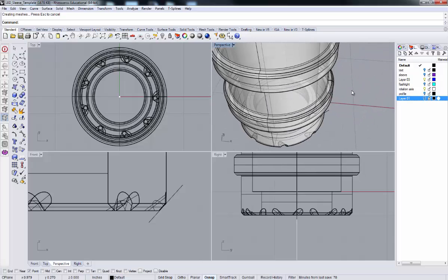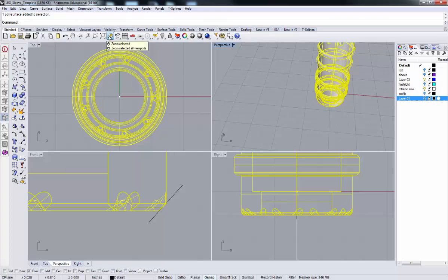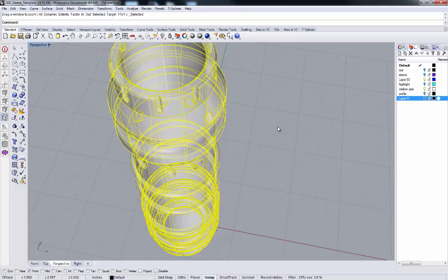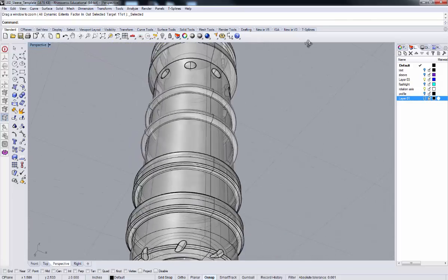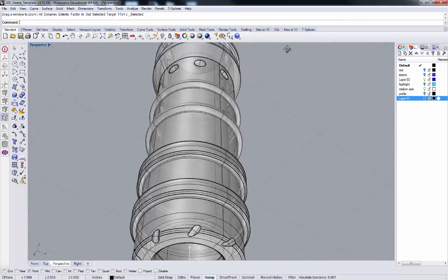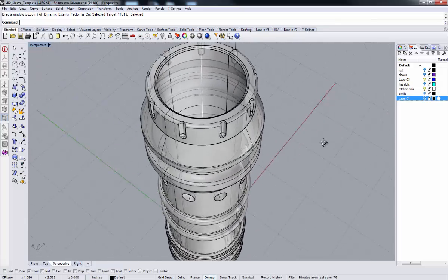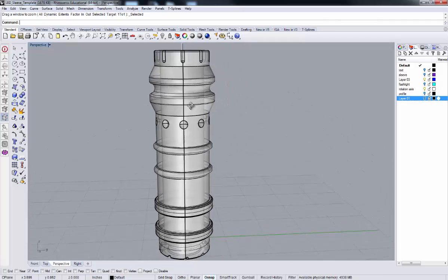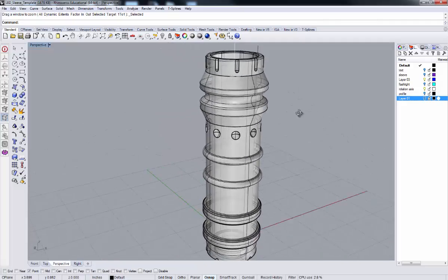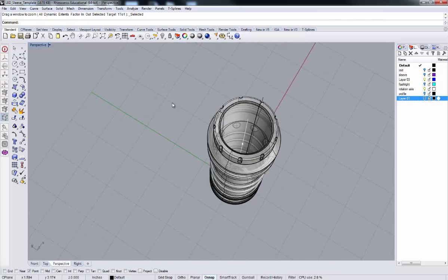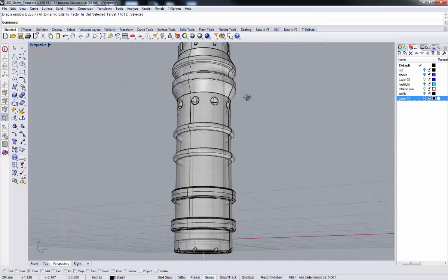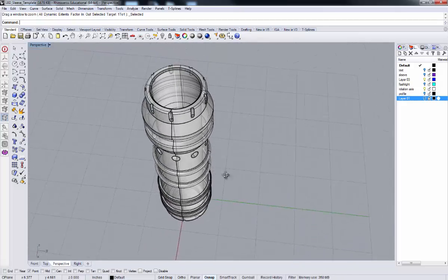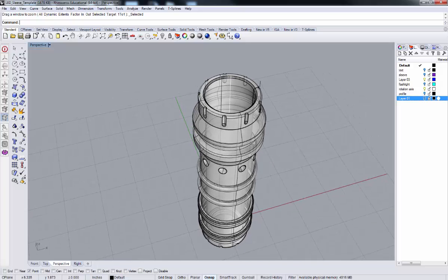And I think for now we'll stop this one here before we move any further. But that's a good way that you can use some solid modeling techniques to add details to your flashlight model. And once again, the main commands are ArrayPolar to array them around the center, and the other commands are your Boolean union, Boolean difference commands. And we'll stop it here.